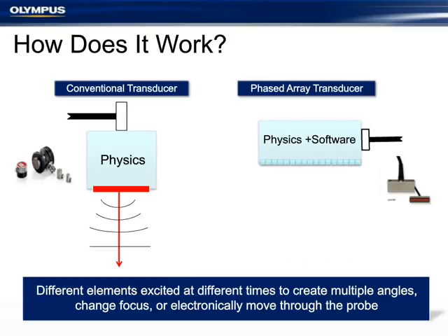The other type of thing we can do most commonly is the electronic raster, where if I was taking a 0-degree probe, inspecting the wall of a pipe, say, for delamination, I would have to physically move that 1-inch or half-inch probe over every little part of that to see if there was any delamination or other defect. Here we have maybe a 2-inch long probe, and we can have the electronics do some level of rastering for us. So we can do very quickly 49, 50 beams in a single probe and just increase our coverage and detection capability.